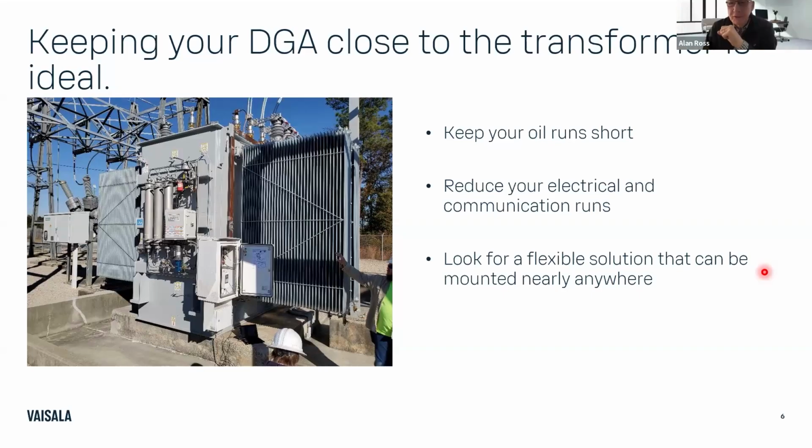All right. Another yes or no kind of answer. Can the unit be mounted directly against the transformer, or will the vibration affect the performance? I think this picture is showing it mounted on the transformer, if I'm not mistaken. Yeah, it can be installed. We do have vibration dampers available for such installation. OEMs, especially when it's a question of a new transformer, make readily available the installation frame there.